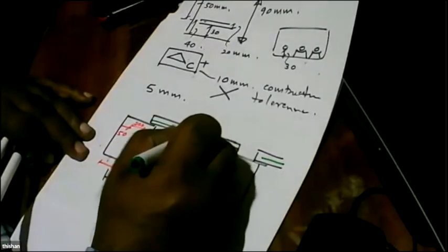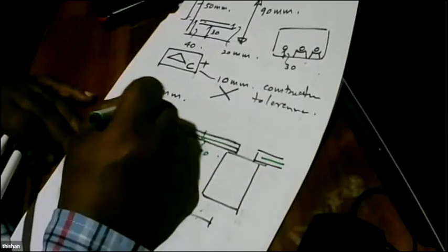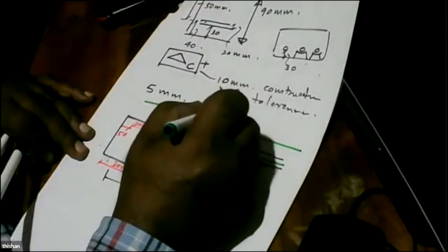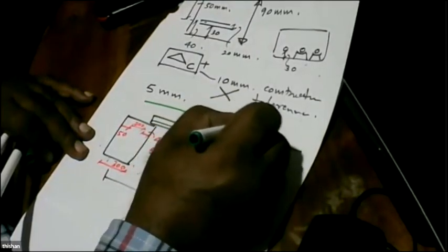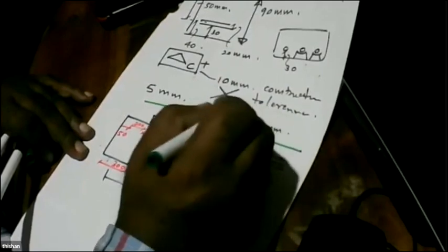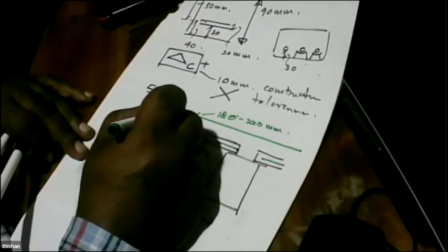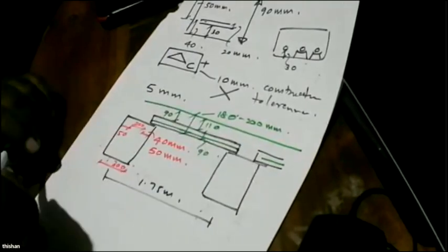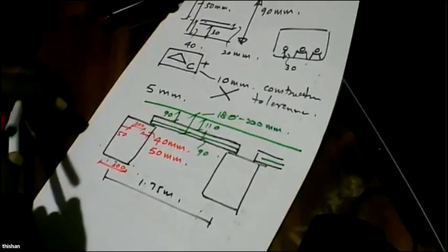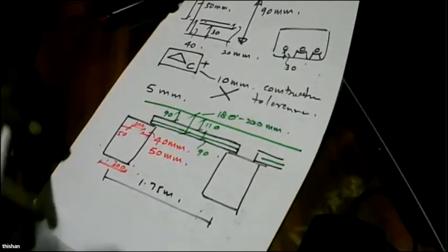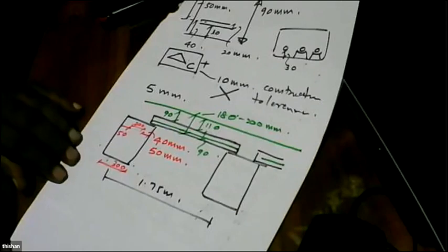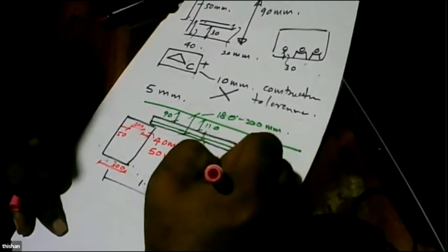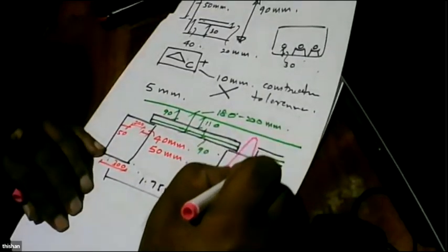Now this is 90 millimeters, and we are going to complete the bridge with an overall thickness of 180 to 200 millimeters. So this can be another 90, or it can go up to 110 as well. That is your preference. But you have to again look at on what basis we get these dimensions, because now we are going to have two types of links here.